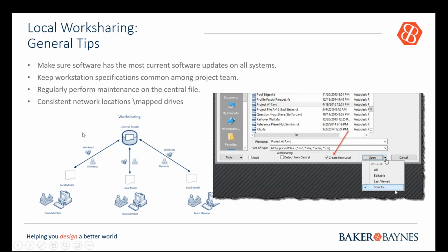All right, so work sharing tips. General tips: make sure the software is up to date. You want to make sure that your release of Revit is the latest one. I'm not talking about year versions. I'm talking about Revit 2020.1,